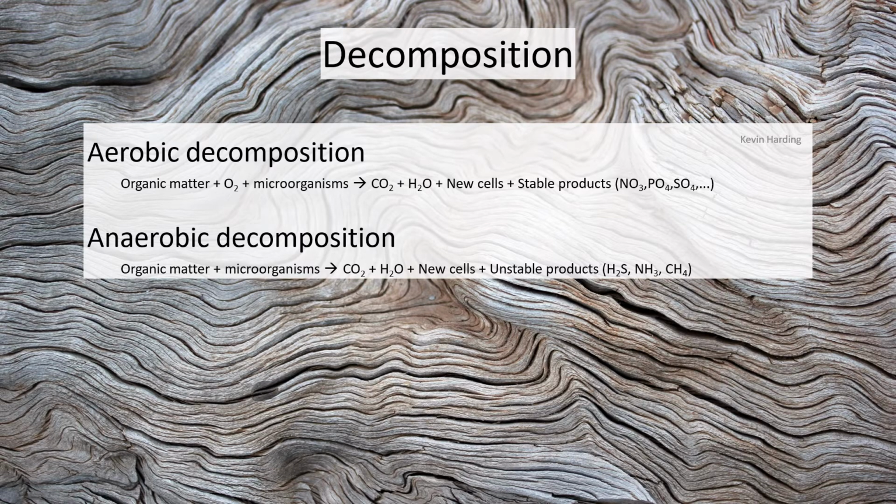When you discharge wastewater, we are then going to have 2 types of decomposition. So the first one is aerobic decomposition, and the second is anaerobic. The difference between these two is that in aerobic, we mean air, and in chemical reactions, hopefully you remember that oxygen is the reactive portion of that, and in anaerobic, there is no air.